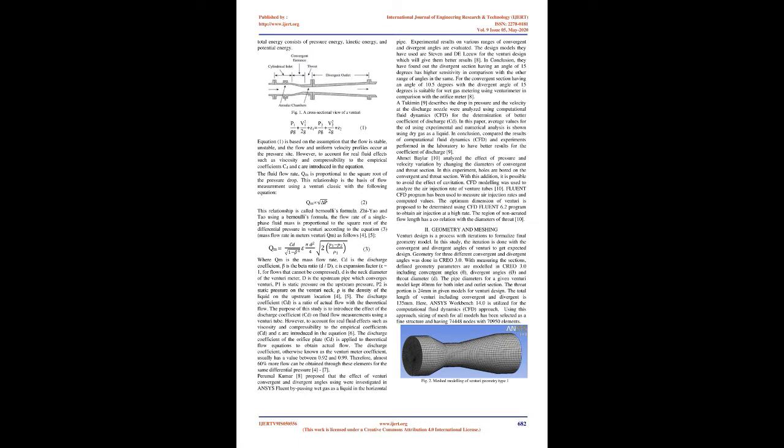Due to the convergent entrance, the speed of fluid flow increases and pressure decreases in the middle of the cylinder neck. Thus, the pressure difference correlates with the fluid flow rate using Bernoulli's equation. The total energy at each point of the fluid is constant. The total energy consists of pressure energy, kinetic energy, and potential energy. Equation: